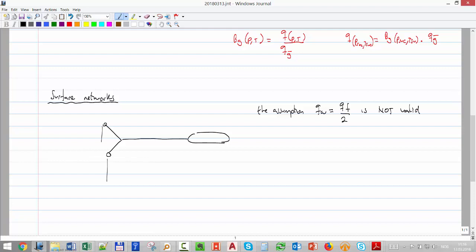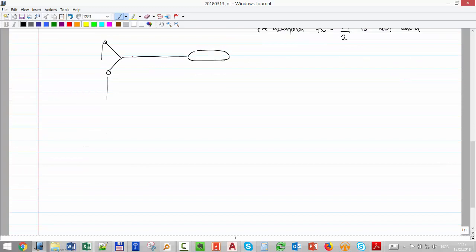The tubing length will be different, the depth will be different, maybe tubing size will be different, the deliverability, the characteristics of the formation will be different. Many different cases, maybe the fluids will be slightly different, so that assumption is not valid anymore. So you have to solve exactly how much each well is producing. For that, first we do it graphically, and then we go a bit into the more formal way to make it.